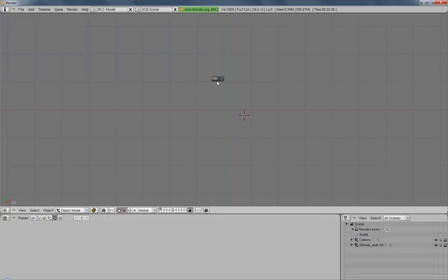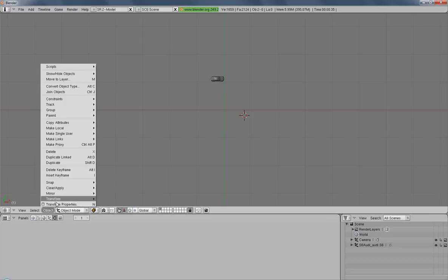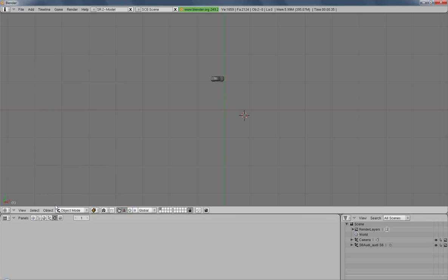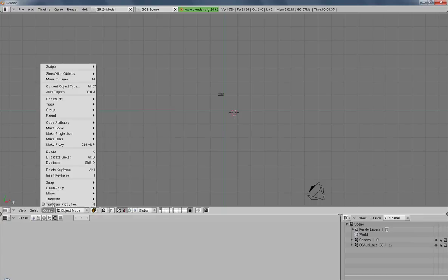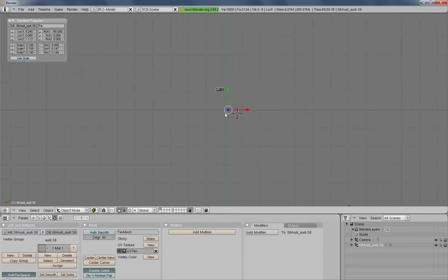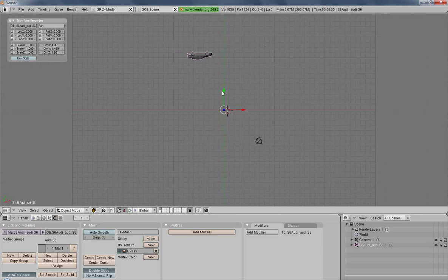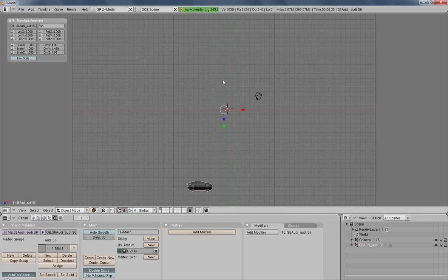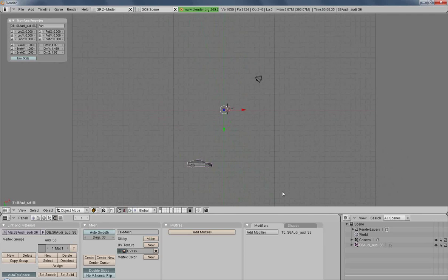So first of all, you can see this car is not standing close to the global coordinate system, so we will have to shift it. I open the transform parameters window here. And as you can see, it's located outside the center, so I first set the pivot point to the center. Also the rotation I set to 0. Scale, I will scale the car to 1, and I will have to zoom out in order to see the car again. Okay, there it is. Now I'm going to rotate the scene to have the car upright again.